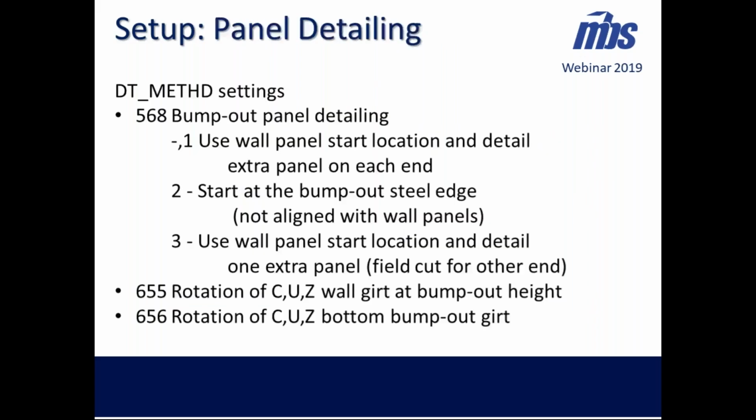What we introduced was some more methods. One was to help you with this panel detailing, and we give you a few options there, which we'll go over in the next slides. We also have methods that help you dictate the rotation of the girts when there are Cs, Us, and Zs that we saw previously.